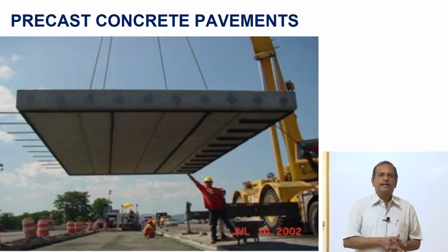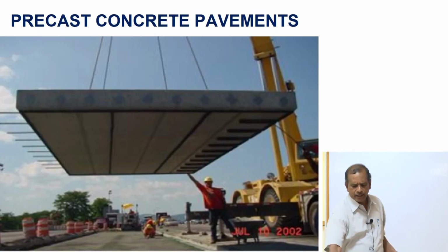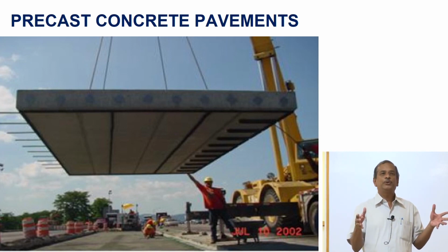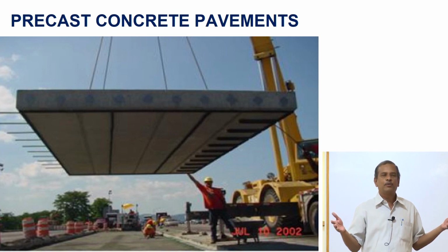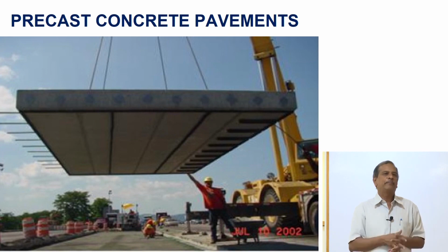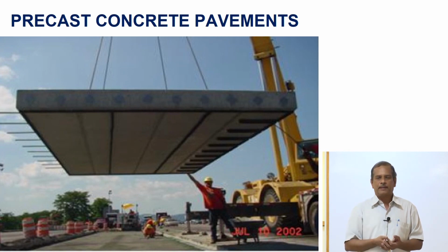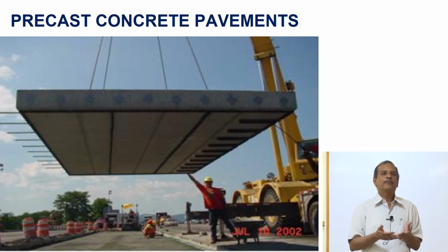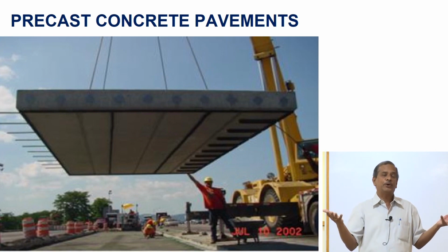So, another thing which I want to introduce is that you can try to have a concrete pavement. As you know, the concrete pavement, you should cure it for 28 days. You can open the road to traffic only at the end of 28 days. Now, those of you from Bangalore will know, a number of roads have been taken up as white topping, a concrete overlay over a bituminous pavement. So, I can construct around 300 meters, 400 meters per day. If I have to have around 200 kilometers, 300 kilometers of roads, it takes a number of days to construct these roads.